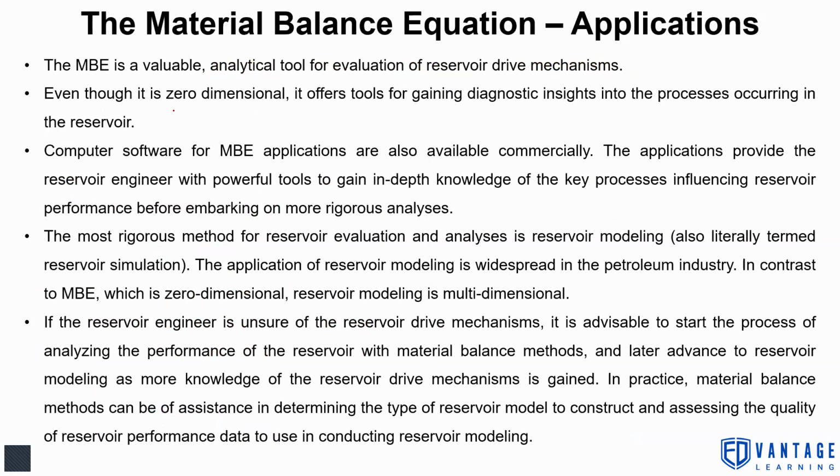I think someone might be having a question why it is called zero dimensional. Zero dimensional means the material balance equation is dependent on a pressure, P bar, which is averaged out in the reservoir. So we assume that the pressure is the same across all portions of the reservoir, right from the reservoir external radius to the wellbore radius. That is why no parameter has any dimension in the material balance equation. We assume that it is a purely homogeneous system and every parameter is averaged out in the entire reservoir.